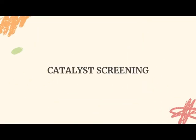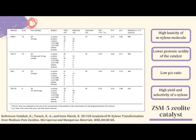Moving on to catalyst screening. The preferred catalysts used for the isomerization process are zeolites. In an article, an experiment of m-xylene isomerization is conducted with 4 types of catalysts, and the results are shown in the table. The high basicity of the m-xylene molecule helps the diffusion of m-xylene through the 10 rings and further isomerization. The positive effect on selectivity is due to the low protonic acidity of the catalyst. IM5 catalyst shows the highest acid sites, thus it is not preferred to be used in this process.